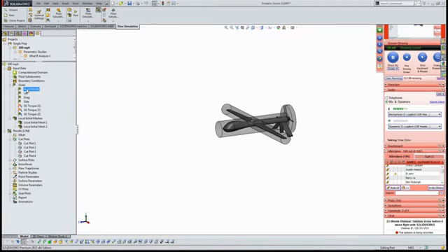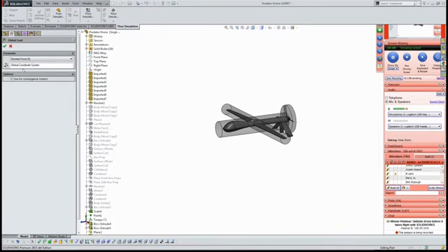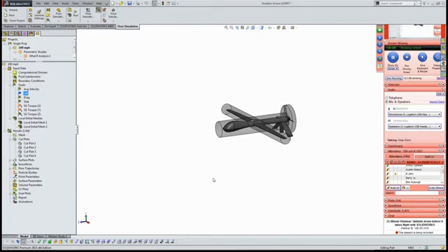The other thing is that I set up some goals. For instance, I set up a goal for drag. That drag goal is just summing all of the normal forces on the solids in the y direction, and I'm using that for convergence. Anything that I'm really interested in, whether it's drag, temperatures on components, average velocities, or lift, I can create goals, I can create equation goals, and then I can ensure that I've got a converged result.